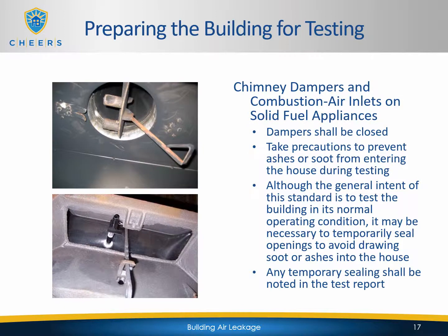Chimney dampers and combustion air inlets on solid fuel appliances. The dampers shall be closed. Please take precautions to prevent ashes or soot from entering the house during testing. Although the general intent of this standard is to test the building in its normal operating condition, it may be necessary to temporarily seal openings to avoid drawing soot or ashes into the house.